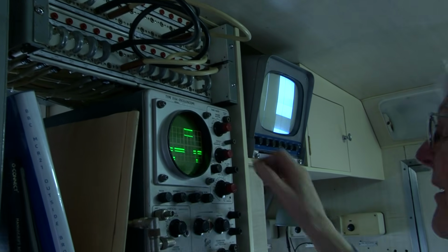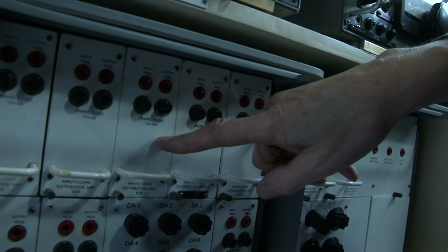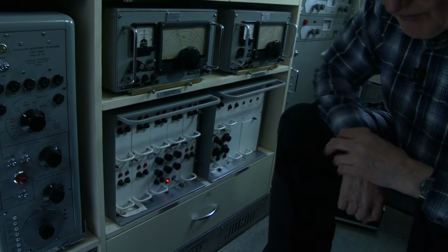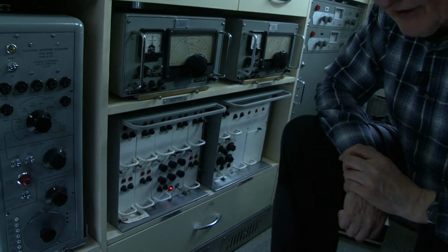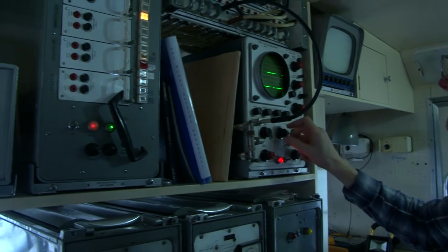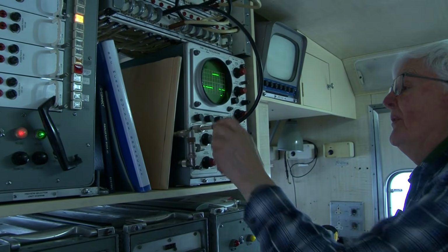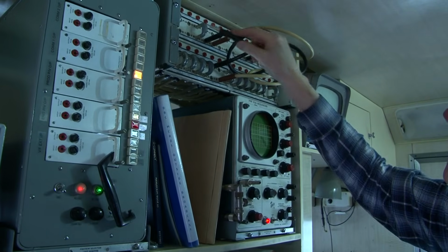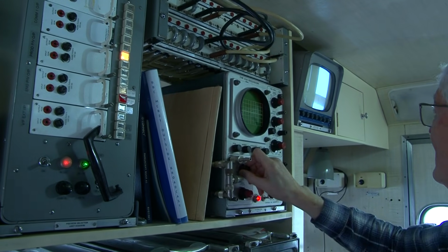Why has it gone hummy? So this is DA3 here, an ordinary BBC distribution amplifier of the period with 3 outputs. It's an AM4/511. Not hummy. So DA2 is unhappy. Let's try DA3. Looks better up there.